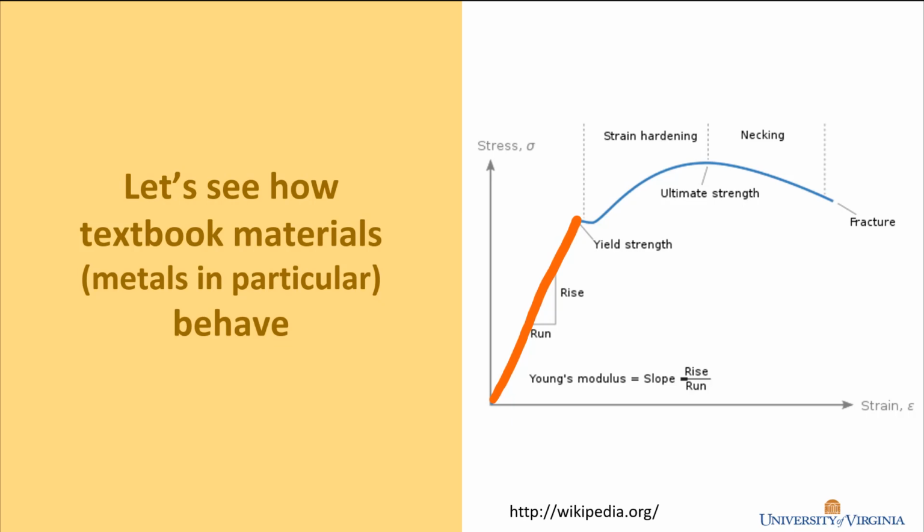Now, when you get past that, so past the yield strength, which is measured by stress, it gets into a region where the part hadn't broken yet, but it's deformed. It's not going to return to its original shape. Like when you bend a coat hanger and it stays in a new shape, right? Hadn't broken yet and it isn't about to break, but it's not going to spring back to its original shape if you push it too much. And then if you go past that, it's where the material is really starting to fail and ultimately leads to failure.